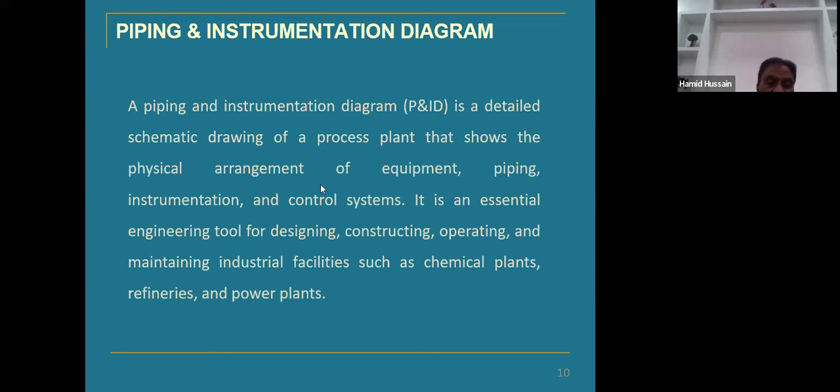For example, if a tank is there, on one page you can show only one tank because it has different incoming lines. For example, a nitrogen line is coming, maybe the main line is coming, maybe the purging line is coming, maybe the drain line is shown over there. So in the PFD, many pieces of equipment are shown on one page, but here it can be shown only on one page. It will have interconnection lines to connect other equipment or other controls, so there will be interconnection lines for the pipelines and interconnection lines for the instrumentation control, which can be hard or soft.